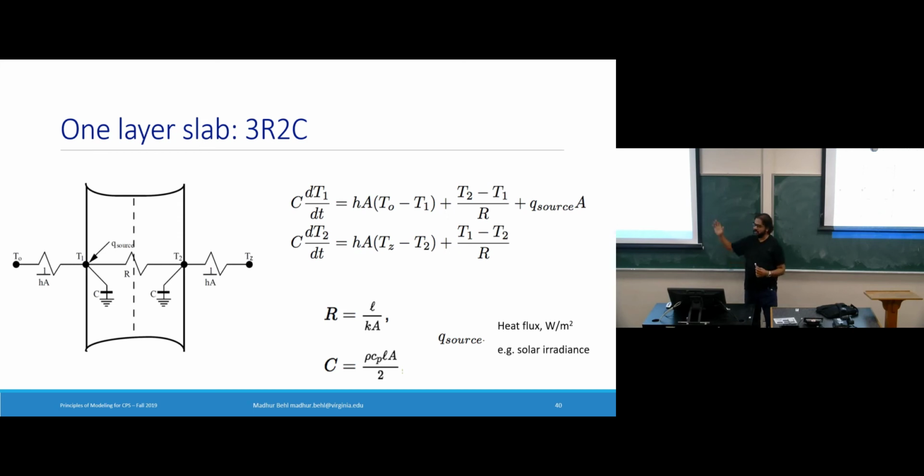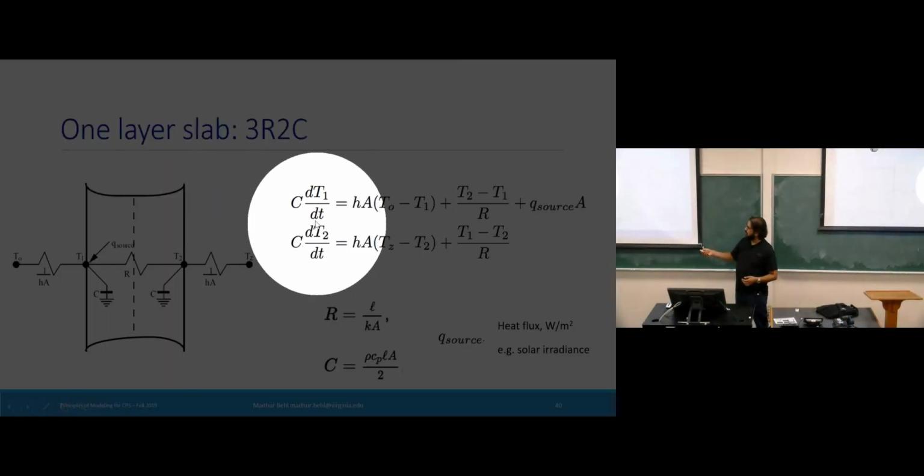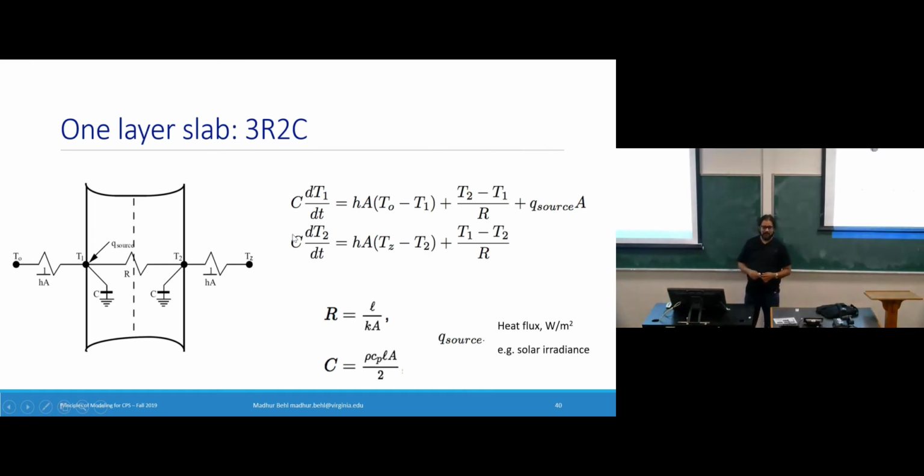T1, T2 is something we have introduced. T0 is the outside temperature. I don't control it. It's not the state of my zone. And the zone temperature could be a state, but in this picture, it's just a boundary condition for convection. In fact, you can see what the state is because the state variables are changing with these dynamical equations. So now, can someone think through of why we need 2 capacitors?